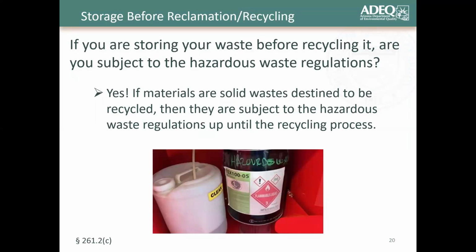And remember, it is stored in an SAA container before it is brought over to the distillation unit to be reclaimed. If you're storing your waste before recycling it, are you subject to the hazardous waste regulations? Yes. If your material ends up with a star in the recycling table, then it is considered a solid waste that is subject to the hazardous waste regulations up until the recycling process.